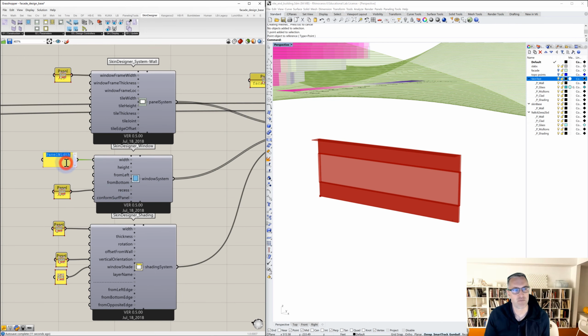We can see if we go into panel width, we can also say times 0.5. This means that the window will be half the overall width. And so now we can see it's centered and it's split the difference between the two. And so if we want to get it maybe close, maybe 0.75 gets us a little bit of wall on either side of the window.